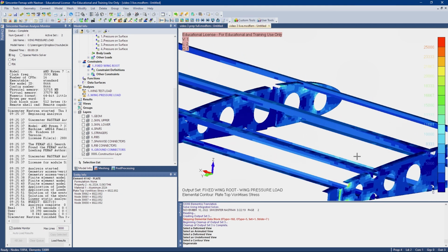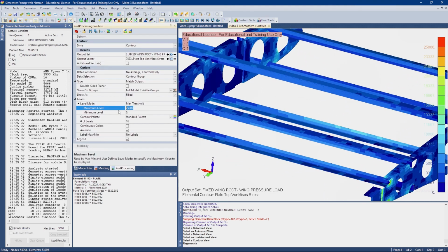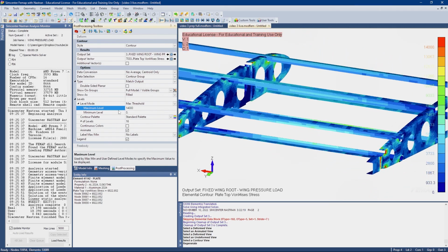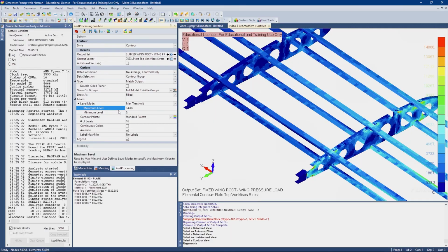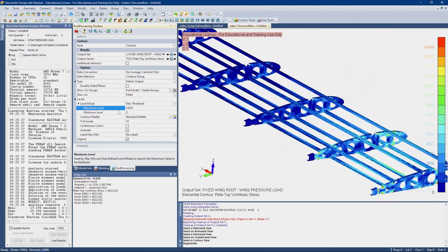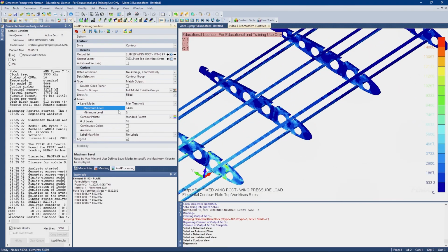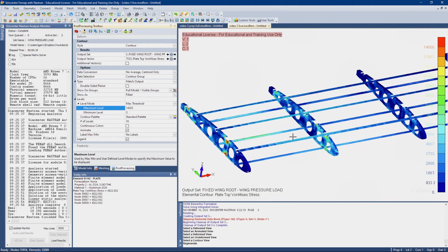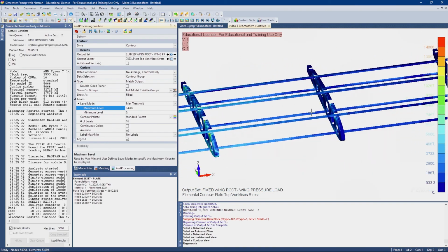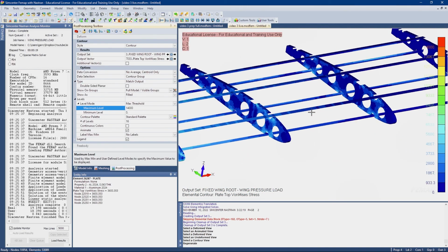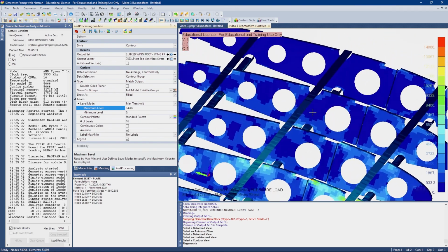Stiffening elements can be a bit deceptive. Even though they have very low stresses, and you might want to thin them out, as you thin your stiffening elements, they take less load and are worse at the job of stiffening the shape of your wing. So even though it looks like maybe we could thin these guys out a ton, you don't want to do it too much because then it loses the benefit it has on stiffening your structure.